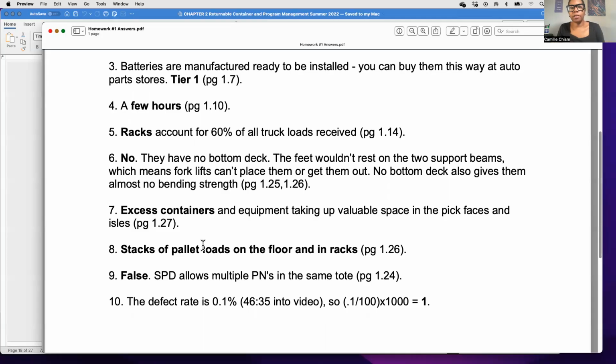It's either something sequenced, or there's some reason why it is, and it's clearly marked. You might have visual management, but there's something that will alert the team to know there are multiple part numbers, so what you won't see is things that look almost identical in the same tote right next to each other. So if you see, in a kit, a left hand and a right hand right next to each other, they're going to be clearly marked, and the left hand will always be on, say, the left hand side, or the top of the bin, and the right hand on the bottom, or the right.